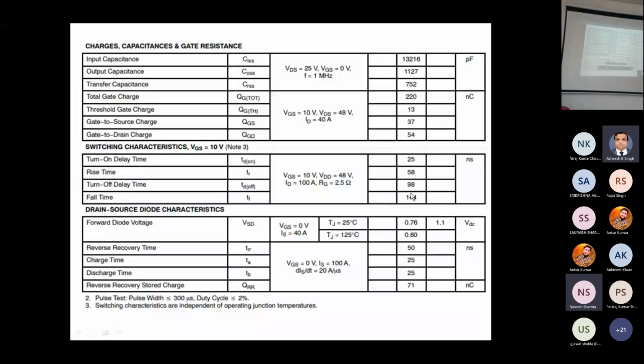If we use a turn on turn off frequency greater than the frequency obtained by this timing, the device will remain in turn on mode or turn off mode, so it will not work properly. So the switching frequency given by the controller and driver should be lower than the frequency obtained using this timing.